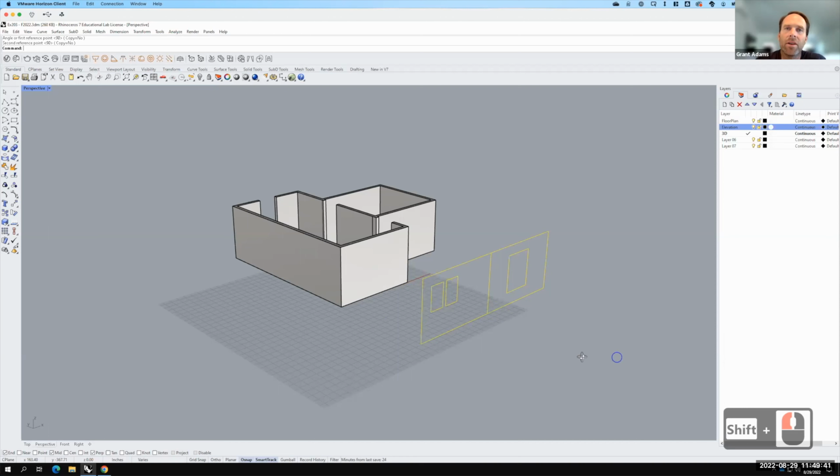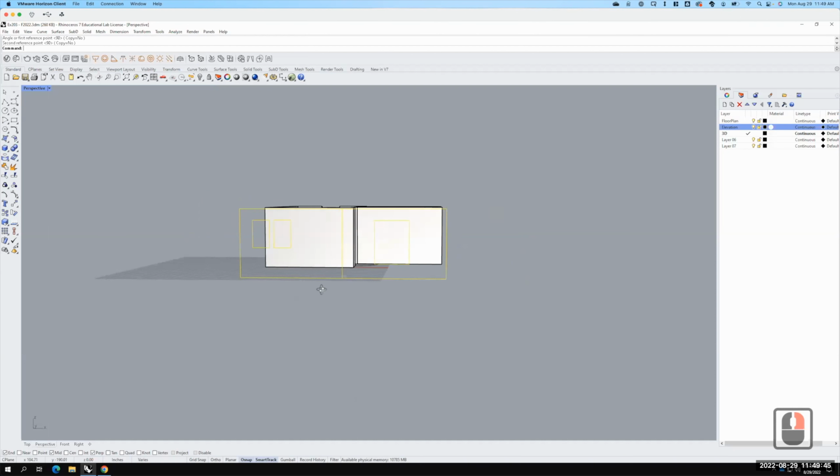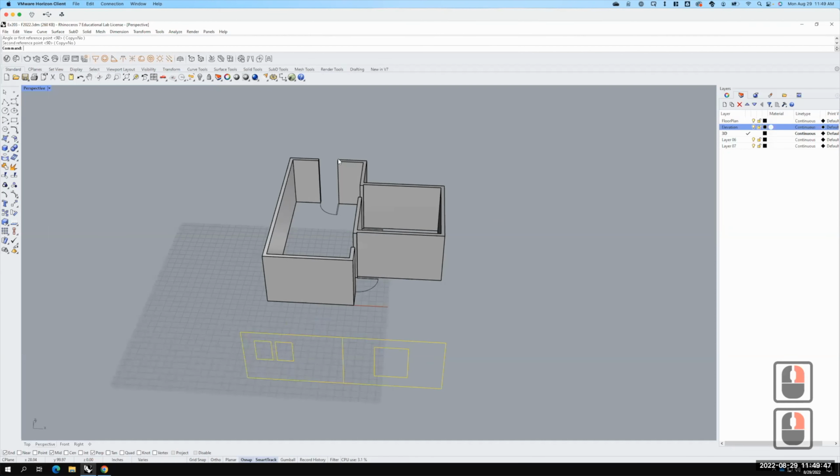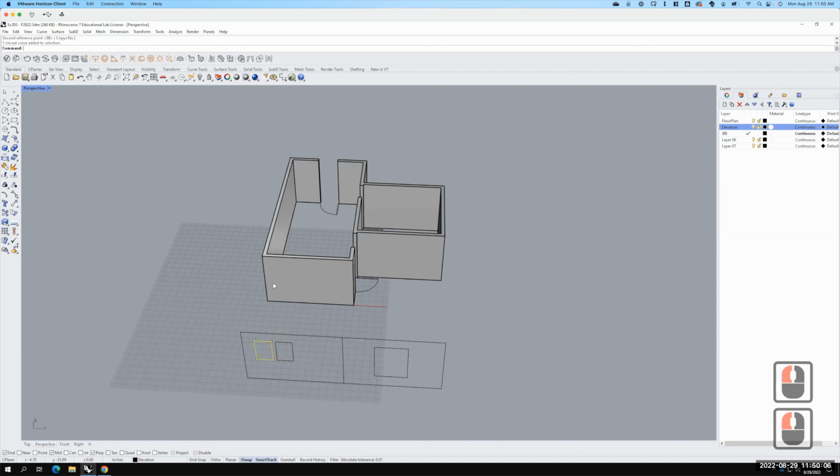So now that my elevation is standing up, it would be nice to take this elevation and basically throw it onto my walls. And so Rhino has a great command for this. It's something that we'll use over the course of the entire semester over and over again because it's a very, very useful command, especially when we have a complex surface and we want to cut it out, for example. So what we'll do is we're going to take this shape right here, and we're basically going to throw it at this wall, and it's going to create a curve that's on this surface for us.